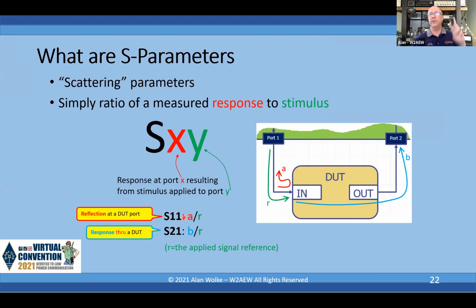Okay, return loss is generally a positive number. The reflection coefficient is a negative number. You just change the sign, and it's essentially the difference between the two. The frequency response, say, of a filter like we did with the tracking generator, is simply the magnitude of S21. Okay.